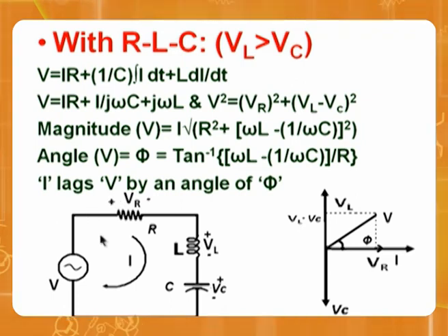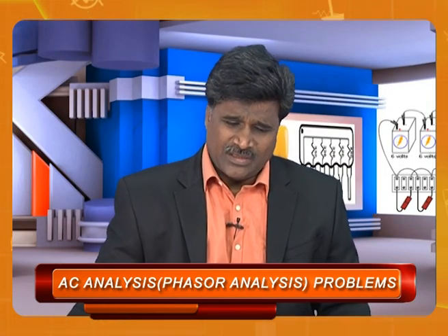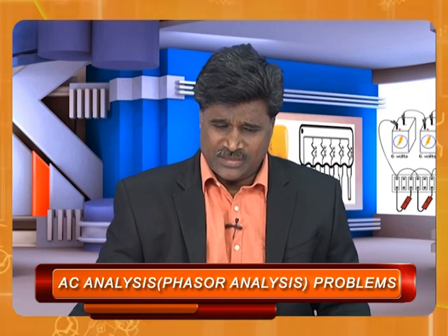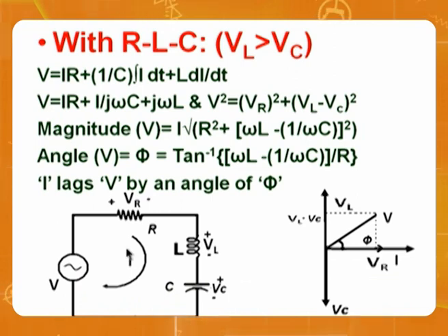Look here, there is a resistor, inductor, capacitor. I saw so many people, and even some textbooks, drawing all three and then making the overall. But that's going to be a laborious one. What I suggest is, since all these are in series, VR is equal to IR, VL is j omega L into I, VC is 1 by j omega C into I. If you take all three and draw the circuit, it will become complicated.